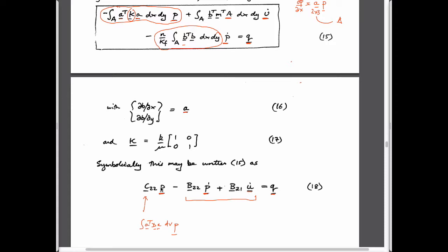Since all of the components in this equation have to be apples, adding apples to apples and oranges to oranges, the apples would be flow rates, and these you could think of as flow rates per unit volume, or volume rate changes per unit volume. This is the volume rate change you get if you squeeze it in deformation and allow that fluid to escape. This is the volume rate change you get if you change the fluid pressure and allow the fluid to compress and then supply a catch-up volume by kicking stuff into it. So those are the basic relationships.